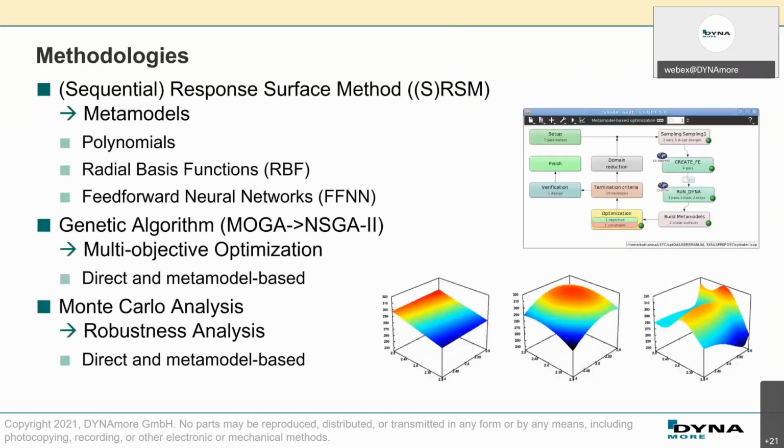The methodologies that are implemented in LSOpt are the following. So in most cases, since we use highly nonlinear applications, usually if you run LSOpt with LSDyna or similar tools, a good methodology is to use response surface methods or the sequential response surface method, which is a very effective methodology, especially for optimization.